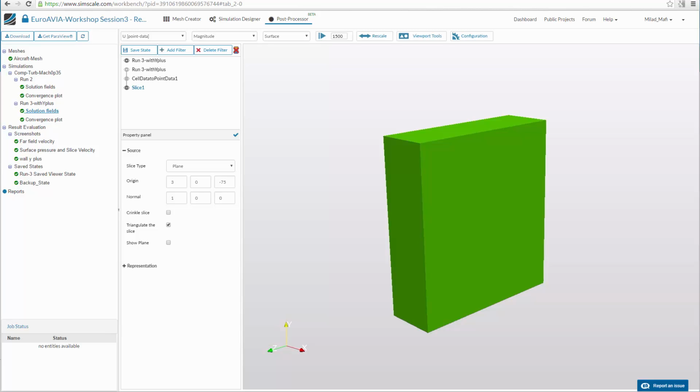The next question is by Otto, and Otto wants to know if it's possible to view the setup as a text file, like an OpenFOAM case, after the setup of the simulation. Yes, Otto, that's possible. For this, you just have to create a report. Let me show you that later on. In the end, you just have to click here to report, create a report, and then all settings will be listed in a text file or a PDF.